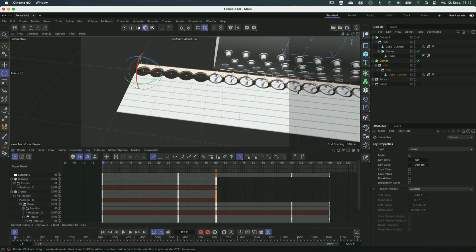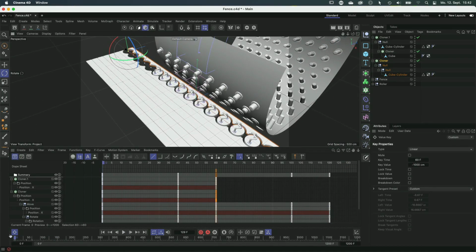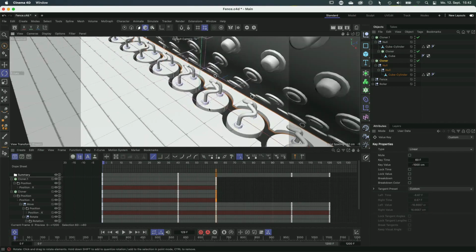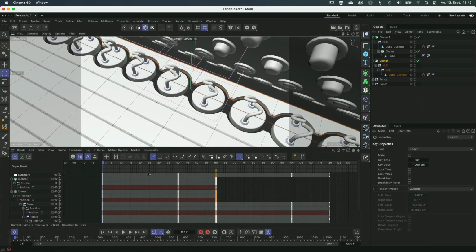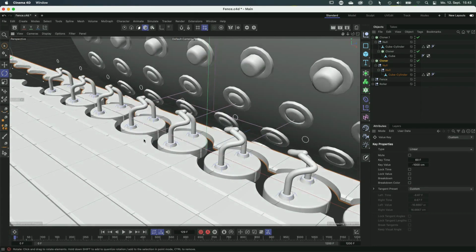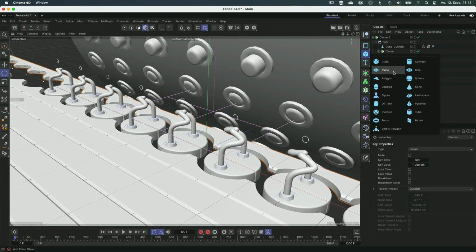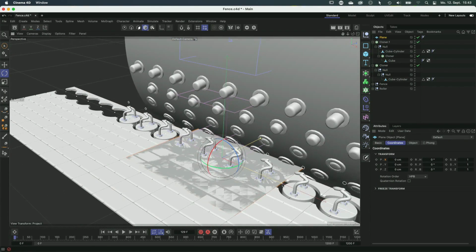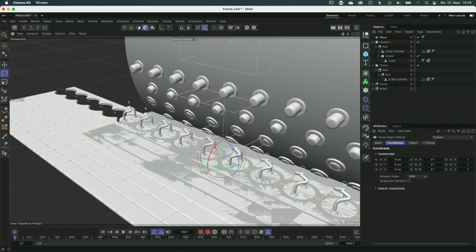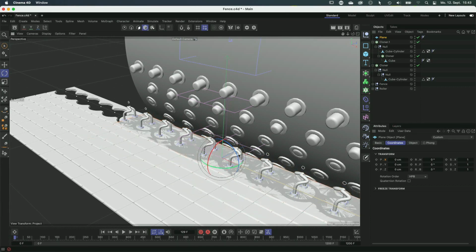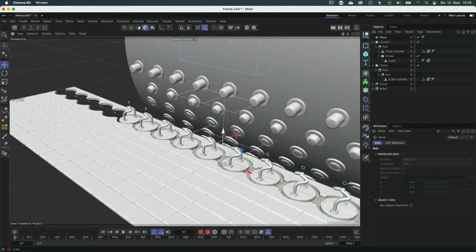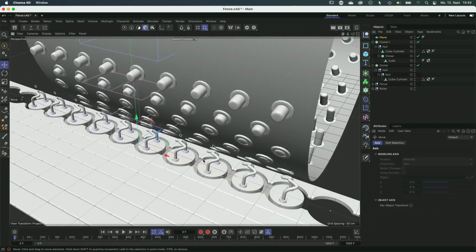And let's finish up the modeling by creating another plane that is just down here, and then we can jump into making this look beautiful. So, let me get rid of the timeline. We don't need that for now. I'm gonna create a plane, make it wider, make it not as deep here, and move it down by 20 centimeters. Here we go. And that's the modeling. Done. Modeling plus animation, done.